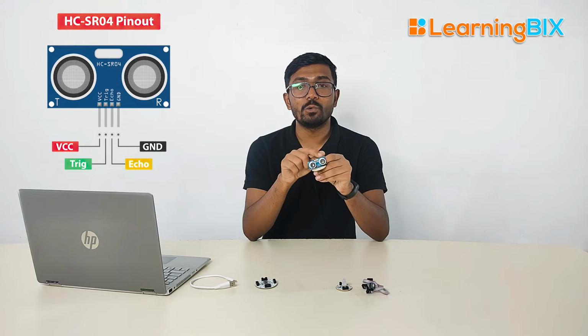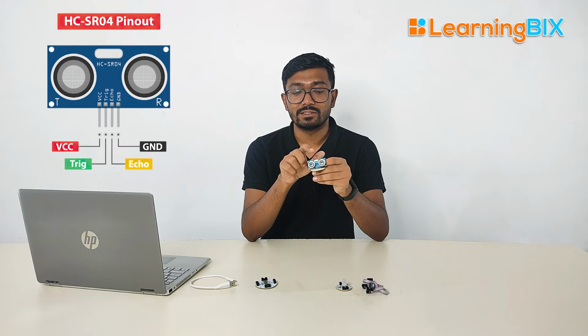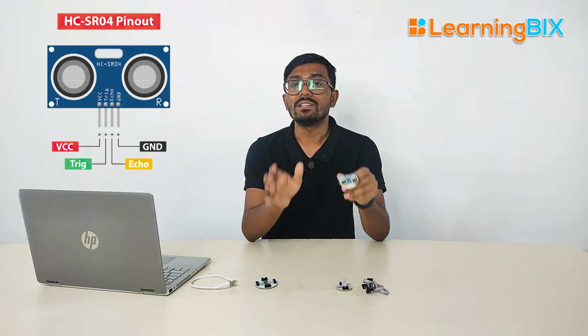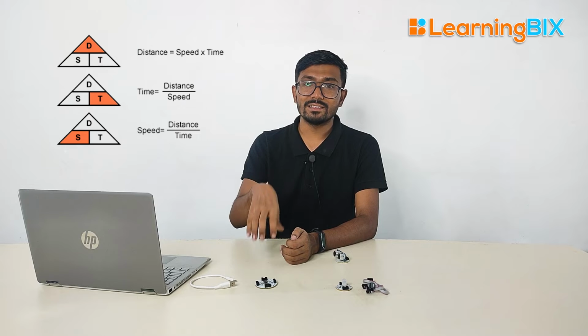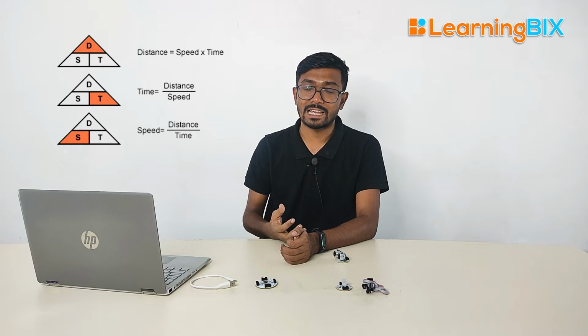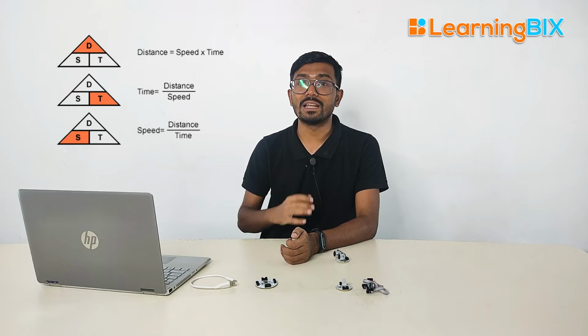Now here we have the ultrasonic sensor which will transmit the ultrasonic sound, and it will also receive that sound. If you see, we have two identical sections. One is for transmitting the ultrasonic sound and the other is to receive that sound, and on the basis of that we can easily calculate the distance. For measuring the distance we have a formula: speed equals distance upon time. By this formula we can easily measure the distance if we have the speed as well as the time.